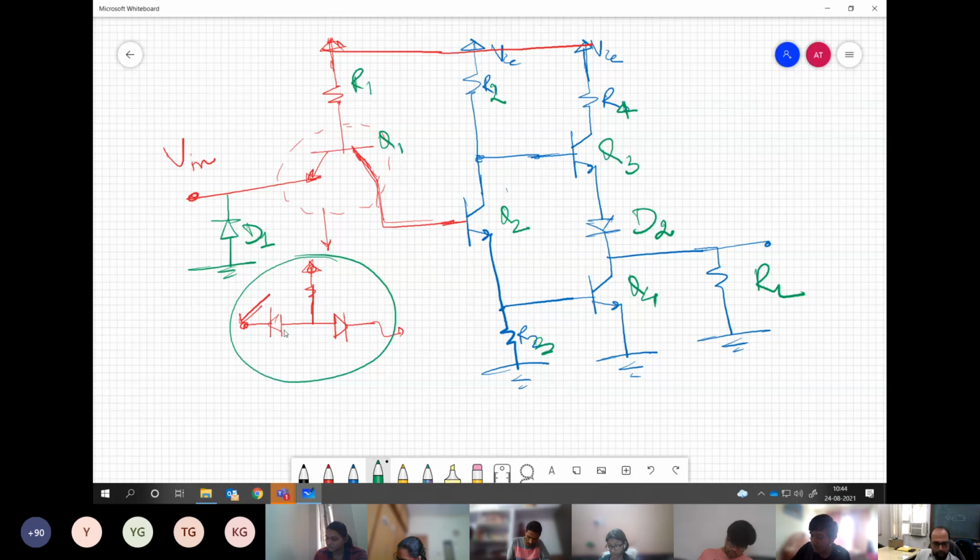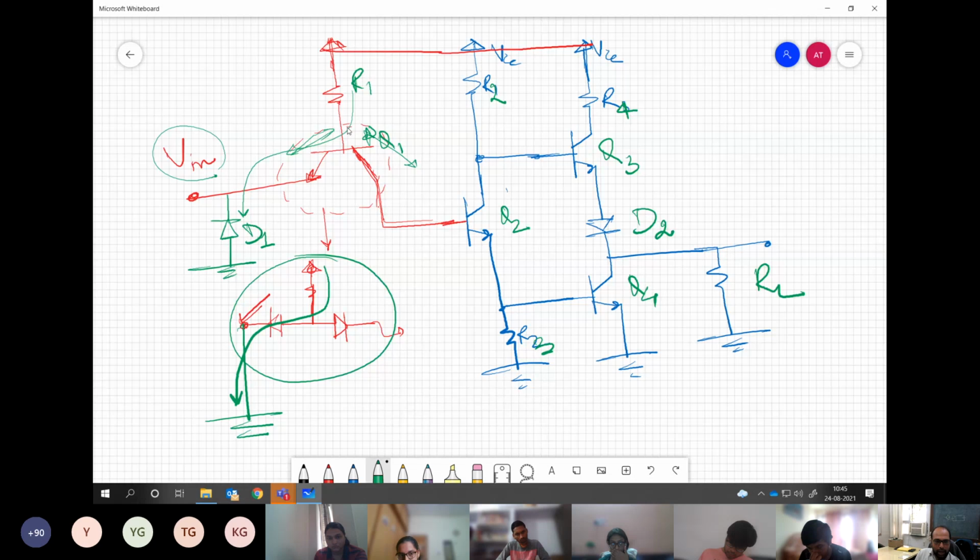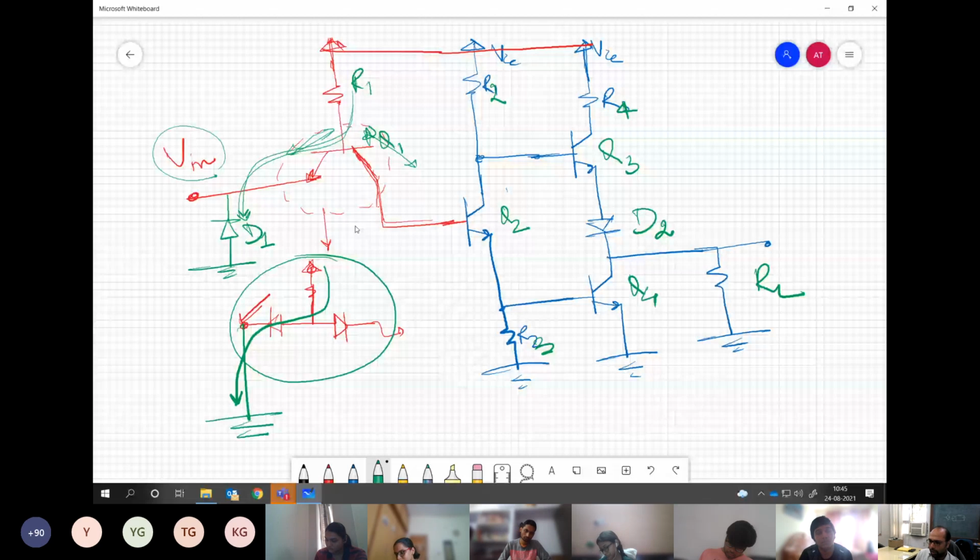What is happening over here? Let us say when you have the transistor in this configuration, the base-emitter junction and this base-collector junction can be driven by this VCC voltage, depending on what input is given. Let us say this input is 0. You are giving 0 input. So what will happen? Your base-emitter junction will be broken and the current will flow like this, which means you are pumping some base current into the transistor. Getting my point?